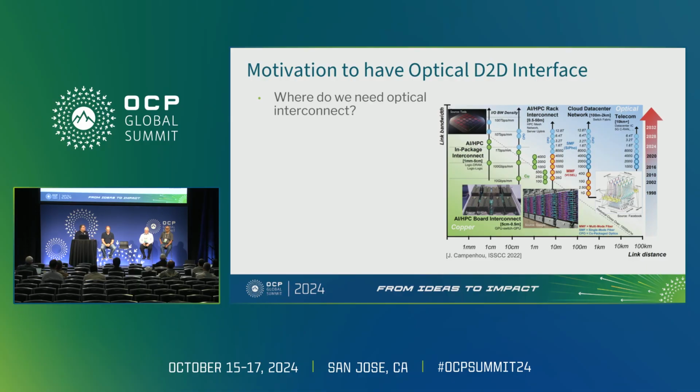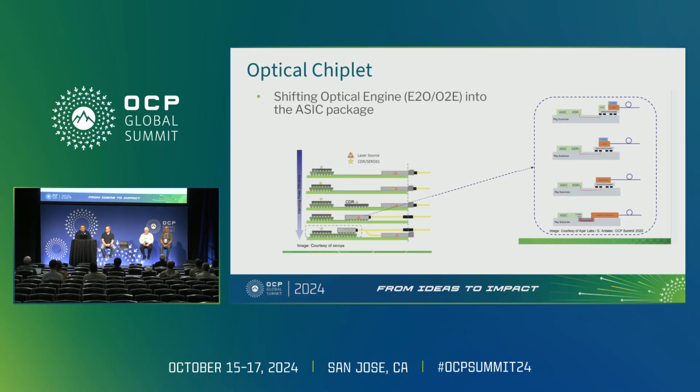I've seen that the best example, and hot in the news, could be Lightmatter and others, that they are enabling this type of link over optical. But there are so many different ways of doing it, in terms of being co-package or near package. If we look at the left graph here, which I cannot see from this screen, maybe I have to look here, the older style was basically leaving the SerDes and retimer all the way at the back of the chassis.